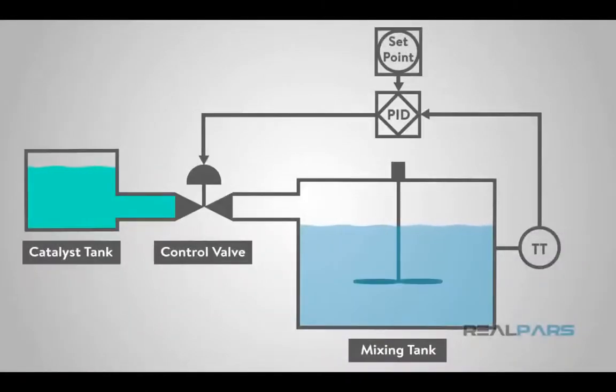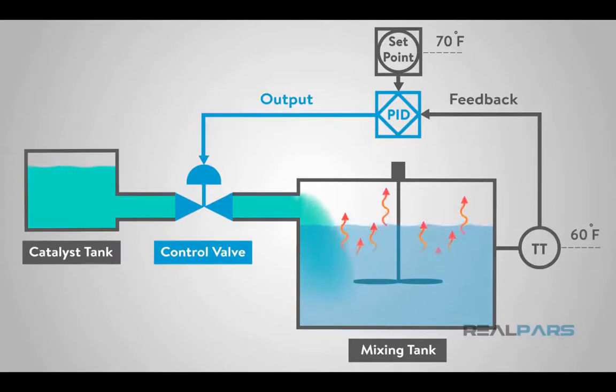In automation programming, we are often required to program a control loop for a given process to control temperature, pressure, flow rate, etc. This requires a target set point with a controlled feedback process variable. A PID process loop controller is designed to generate an output that causes some corrective effort to be applied to a process so as to drive a measurable process variable towards the desired setpoint value. The controller uses an actuator to affect the process and a sensor to measure the results.